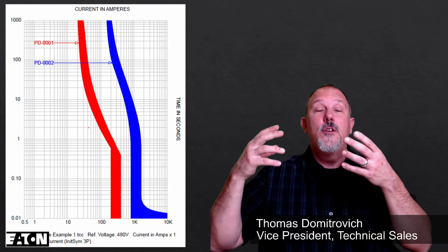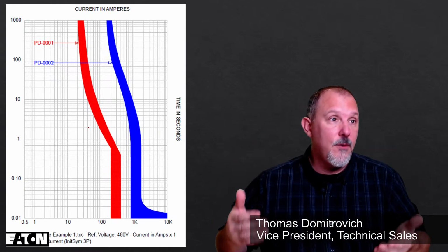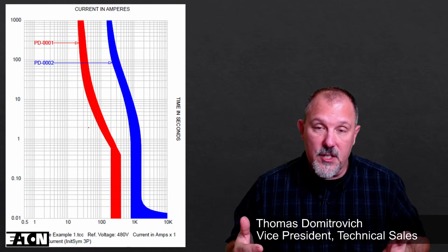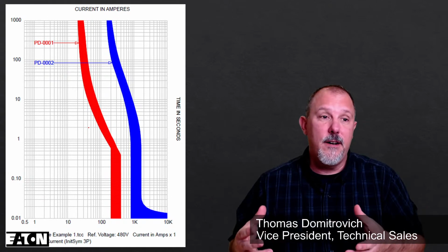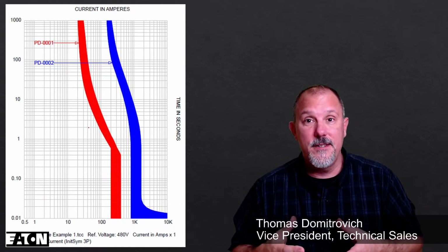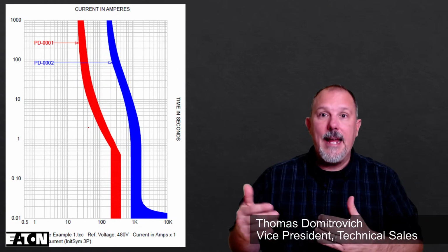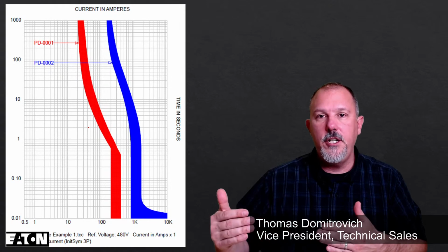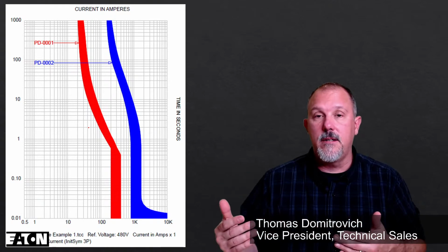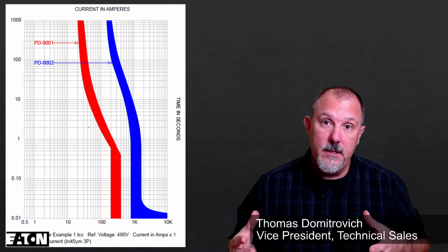We have differential relaying, we have arc reduction maintenance switch, we have arc quenching technologies that we didn't have back in the day. So today I could achieve selective coordination and give you a system that has minimal damage.